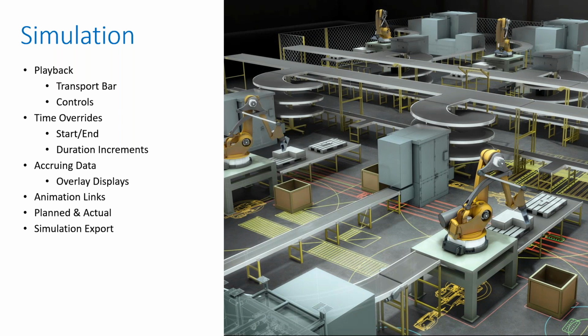We'll have a look at how we can override the times. So for large construction projects which take many months to complete, you can change only the particular times you want to look at. We'll look at duration increments, which governs how long the simulation playback will be. We'll look at adding overlay text on top of our simulation to show how cost increases and how time passes.